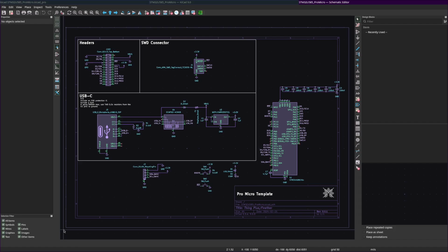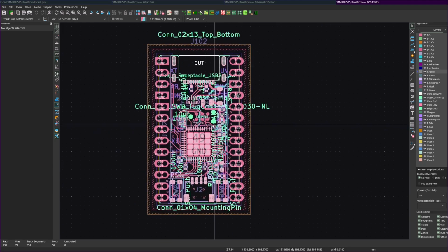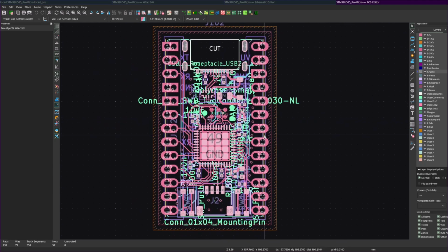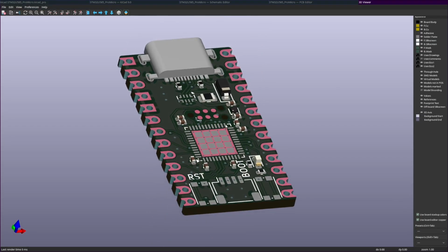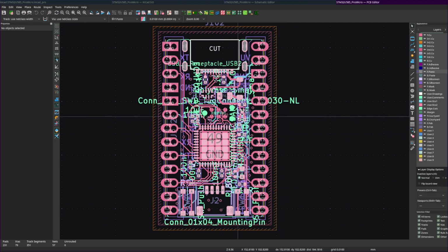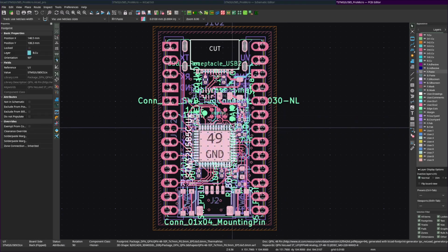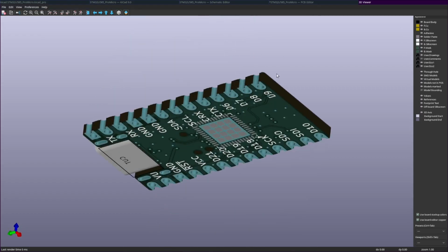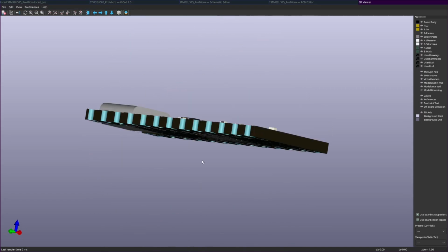Our frame story here is this STM32U585 Pro Micro. There's not a whole lot going on here. It's really just that STM32, required passives, a regulator, protection IC, and then a Stemma port. Taking a look at the board, it's an 8-layer board from JLC PCB with castellated edges and a couple of buttons. Not a ton going on here, which makes it a little bit more embarrassing that I managed to flip the QFN. Let's get a reenactment going here. Yep, that's not going to solder right.